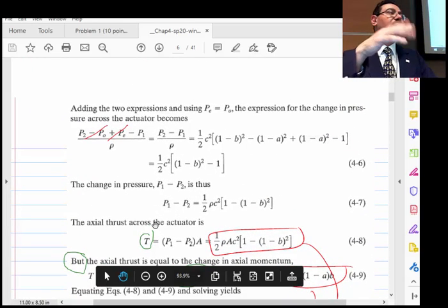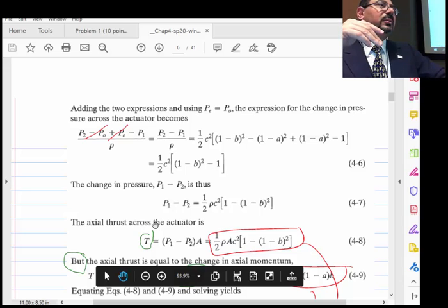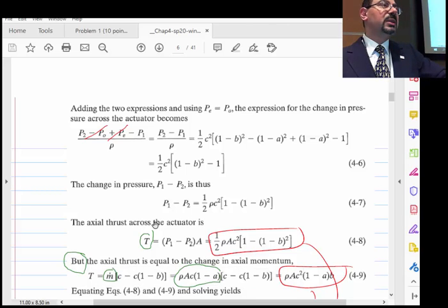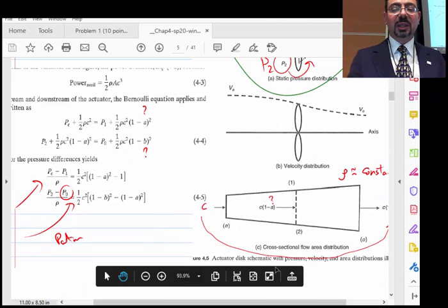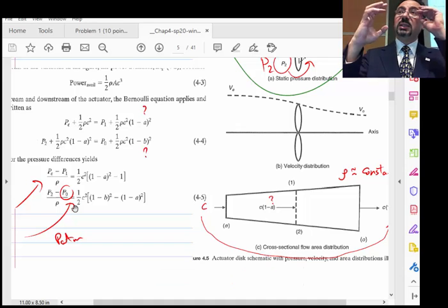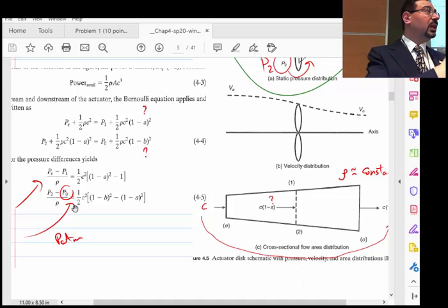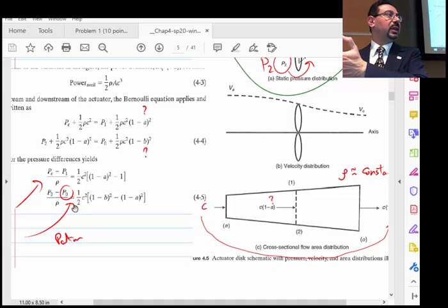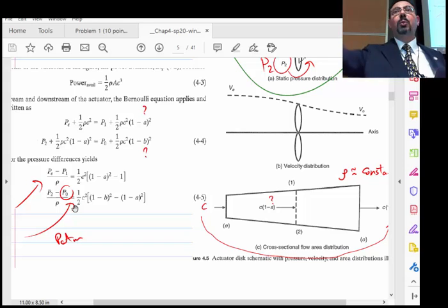The continuity was the fact that we said m dot here is the same as m dot here. That's why he's multiplying by the same m dot. From steady state, whatever kilogram per second is coming in needs to equal the kilogram per second leaving. Otherwise, the thing will blow up in a minute if you have a discrepancy between the inlet and the outlet m dot.